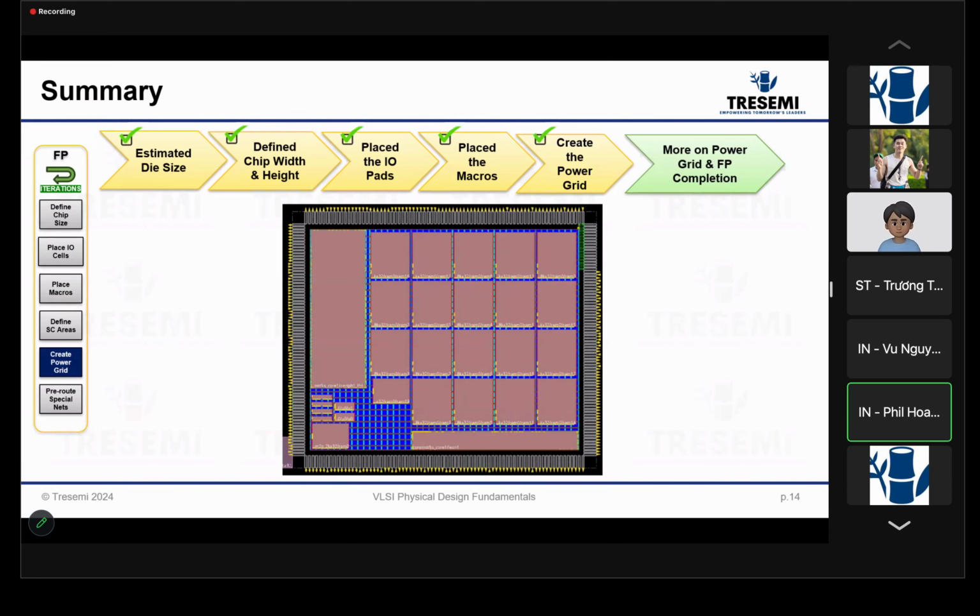So I'm going to cover that. I'm not sure what you mean by assertion, but we do have power grid analysis, which is the step that we want to do to validate that the power grid doesn't have any EM violations, no maximum IR drop violations, no DRC, etc. There are steps that we need to take to make sure that we have a high quality and clean floor plan before we actually do the placement.